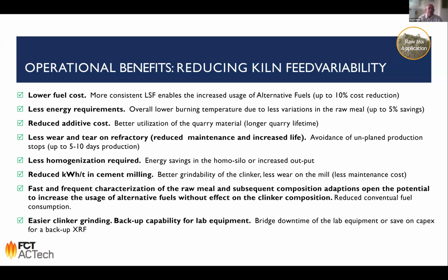And of course, if you have a very good homogeneous material going into the kiln, you will see that you have less wear and tear on the refractories in the kiln. So you can increase the lifetime of the whole equipment, and you will see that this will also, in the long term, remove the unplanned production stops.